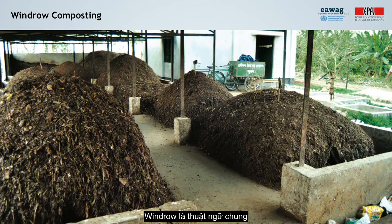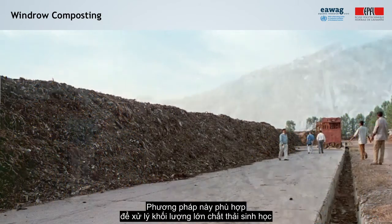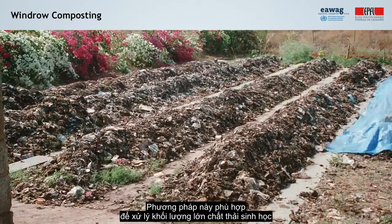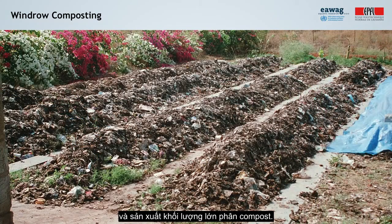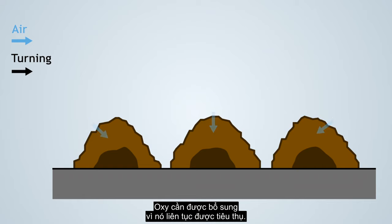Windrow is the general term for an elongated pile of stacked raw materials. This method is suited to treat large volumes of biowaste and produce large volumes of compost. Aeration of the material is crucial. Oxygen needs to be replenished as it is consumed, otherwise the piles go anaerobic in the center, following a different decomposition process and producing foul odors.